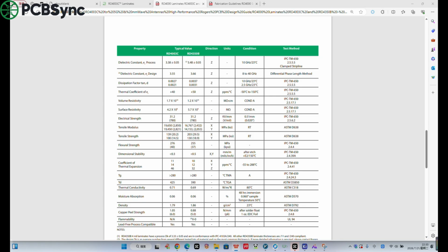The common standard core thicknesses for RO4003 include 0.203, 0.305, 0.406, 0.508, 0.813, and 1.524 mm. After determining the board thickness, you also need to include the copper thickness, impedance layer, and final laminated thickness in the impedance model.